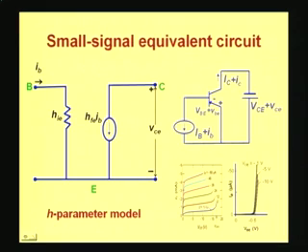So this is the collector to emitter voltage applied. Since the collector current is changing in response to this, you put a resistance here, and then since the emitter base voltage also is changing a little bit in response to VCE, this is shown by a dependent voltage source.